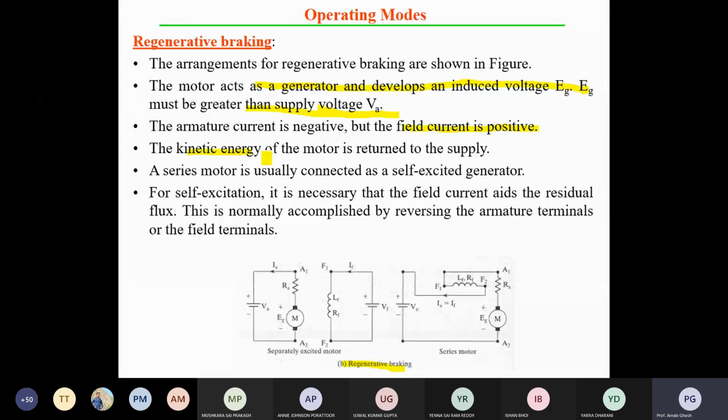So that you can understand, last class one question came about this. This is for the series motor, so the configuration has changed. I am telling you the special configuration: you have to reverse the field, and a changeover switch is there for that. Otherwise, you know the demagnetizing effect. If the current direction in the field is different, it may cause demagnetization or damage to your main field.